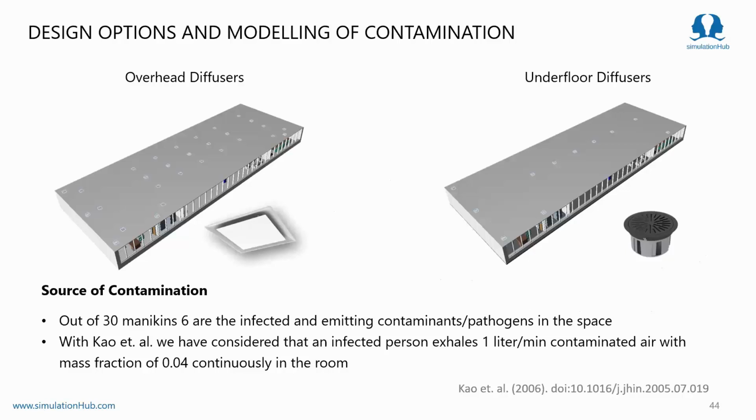Now let's move to comparing design options. Initially, we will first compare the CFD results of the overhead diffuser with the underfloor diffuser. And I already said the 6 mannequins are infected ones. So we model the contaminant released by each mannequin with respect to Cow et al. We exhale 1 liter per minute of contaminant air containing a mass fraction of 0.04 pathogens into the room continuously.